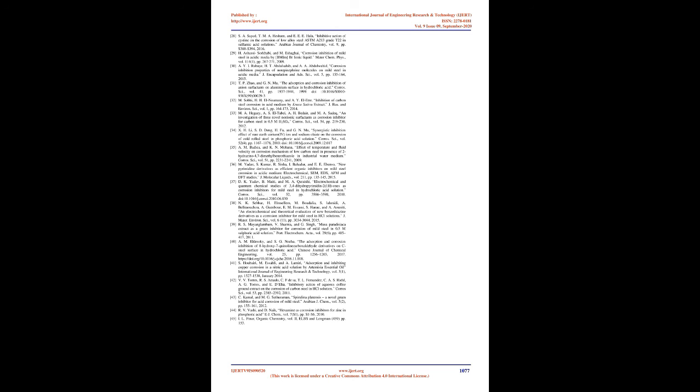The presence of 6 ethylene groups also helps to enhance electron density at the nitrogen atoms, which enhances its adsorption on the metal surface. This in turn leads to an increase in macromolecular size, and the higher number of N atoms of hexamine 45 might have covered almost all active sites of MS. Hence the mechanism of the inhibitive action is probably due to the blocking of anodic and cathodic sites by adsorption, which enables the formation of a protective insoluble film.